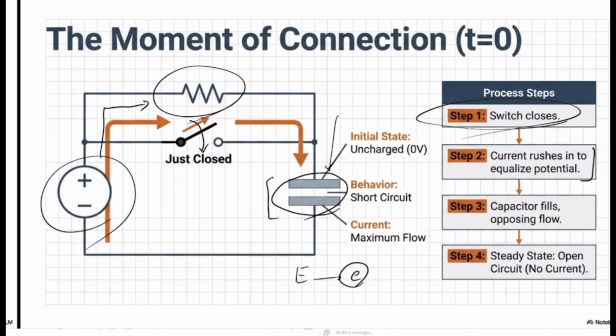It means that the amount of potential or voltage inside your capacitor is not going to increase fast. It's not like this. The voltage inside is going to increase like this. At the very beginning, when you don't have any electrons on your capacitor, the amount of electrical field is 0. It means that your voltage is 0. At the beginning, your capacitor is going to act as a short circuit.